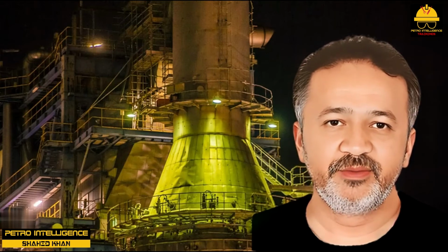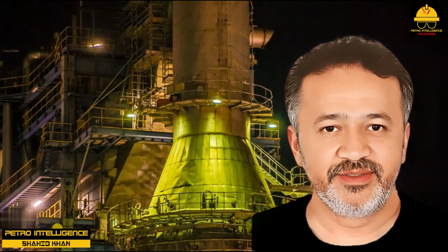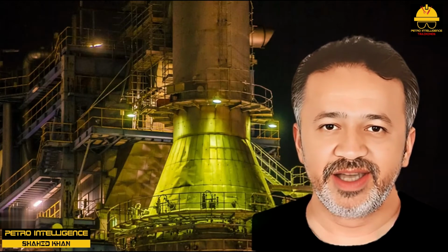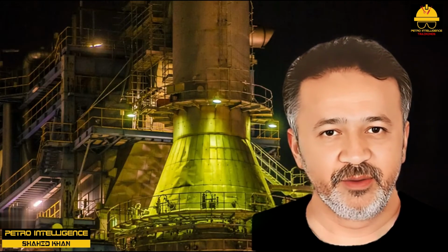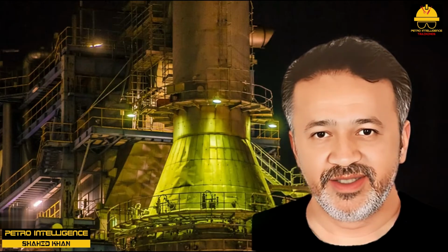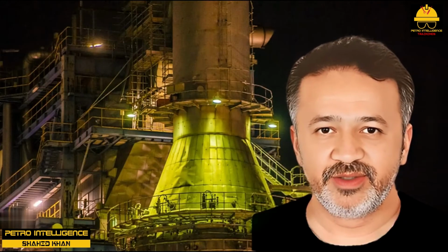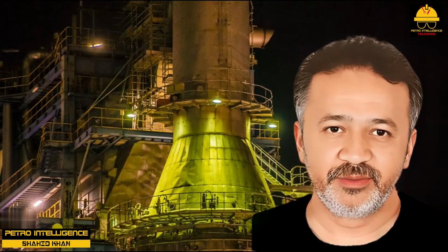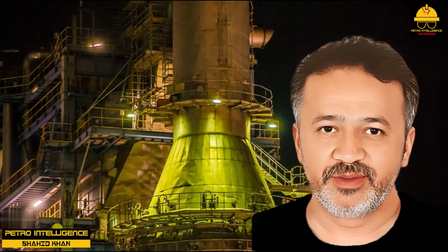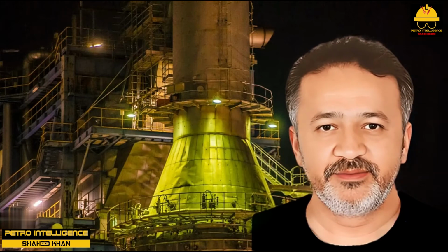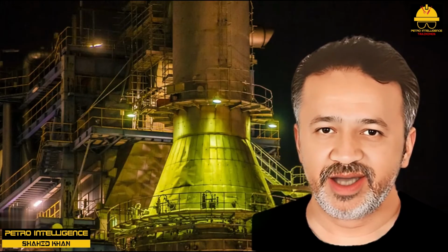At this point, black smoke started coming out of the stack, and several of Operator B's colleagues began to suggest that they should start to open up the air registers and increase the combustion air and not reduce it any further. However, Operator A, now reading 6.5% O2 in the convective section on his O2 analyzer, was determined to reach his 6% O2, and requested a further cutback on the combustion air. When the combustion air was cut back this time, fire started to come out of the stack. Now Operator A was forced to admit that they would have to increase the combustion air again.